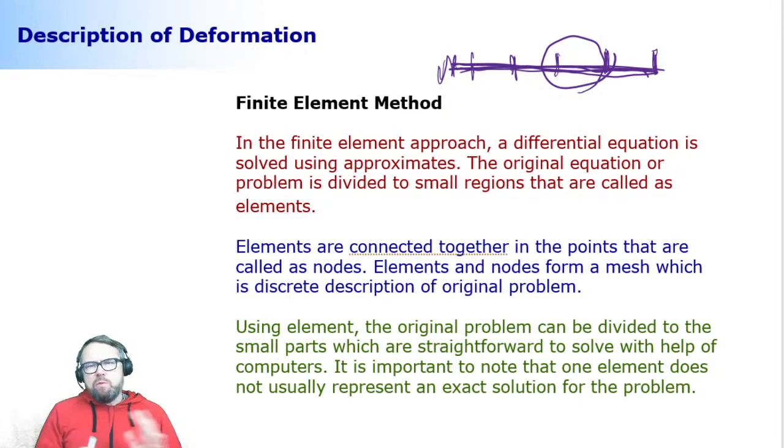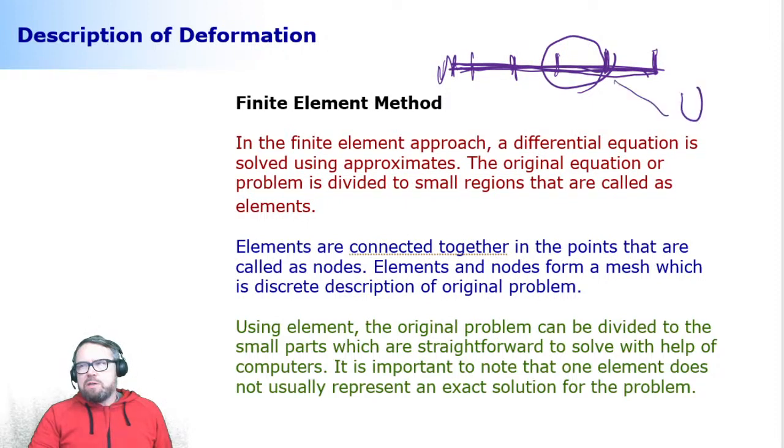We can basically use almost any kind of elements we want, because at the end of the day, what we want from our model is this description of deformation. Most of the elements are capable of doing so. So we are not limiting ourselves to beam-like structures or shell-like structures or solid-like structures, but anything you want.